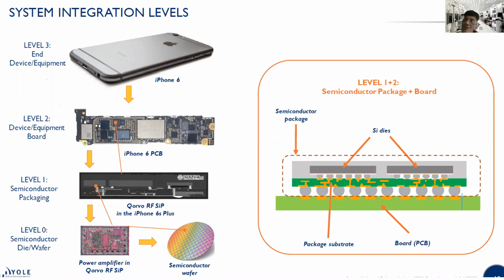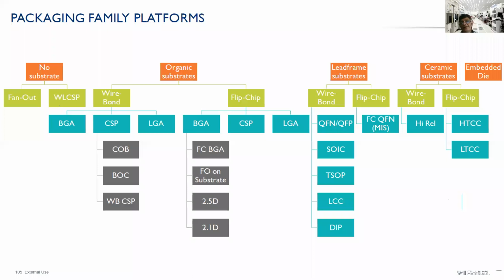But how you reach there is a major technology journey, because you have to not just make these connections, but make sure that they are done right. If there is any oxide bump left in a solder ball, it can have tremendous technical implications. So there's a lot of finesse to that final device that takes place.